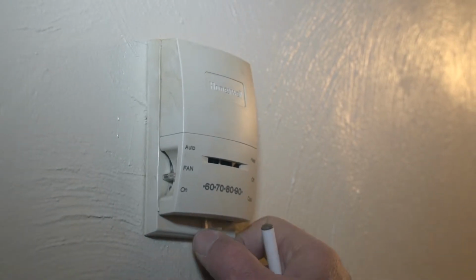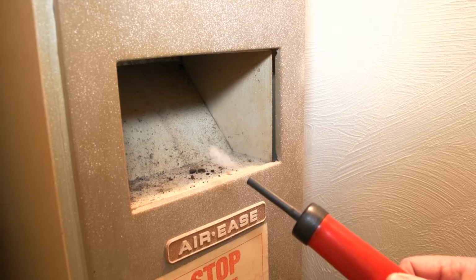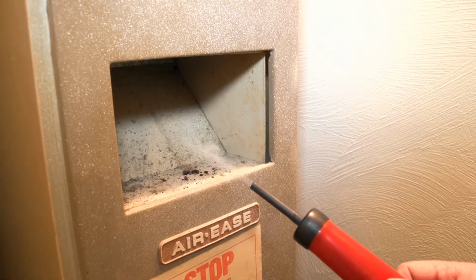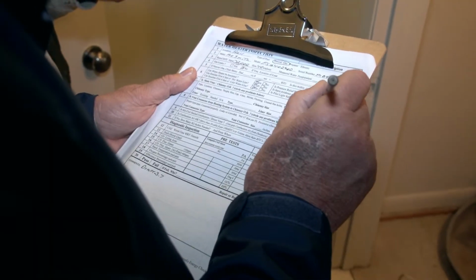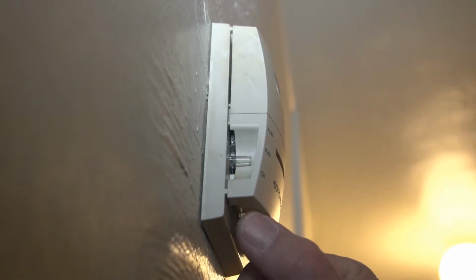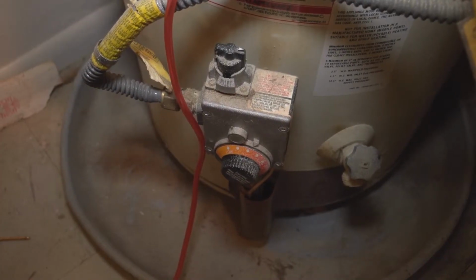So we'll perform the same series of tests that we did with our water heater. We'll go ahead and turn the furnace on, we'll check for spillage, and then we'll verify draft. Once again, if this appliance passes our draft protocols, we'll record that and shut it down. At this point, if both of our appliances have passed draft individually, we can go ahead and test them now together. Now, whether these appliances are commonly vented or individually vented, we're going to want to make sure that we test each one with the other one running.